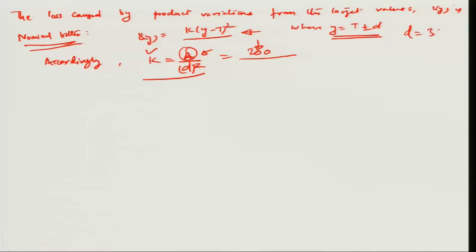You have to remember the D in this case is 35 RPM. So, whatever be the range over which the first to second gear shift would automatically happen is now shifted by a maximum of 35 RPM, beyond which the trucker feels really uncomfortable.